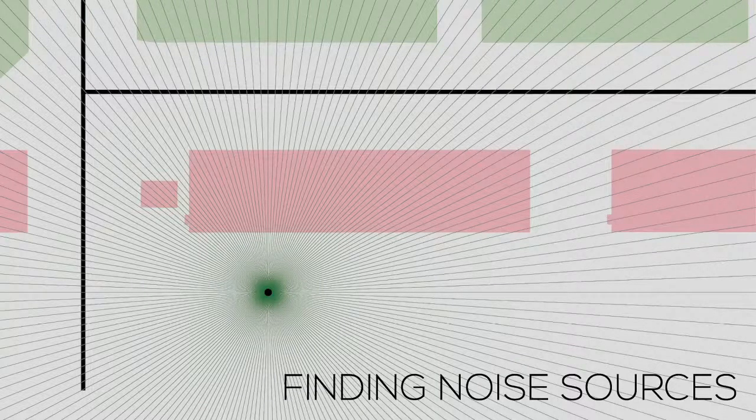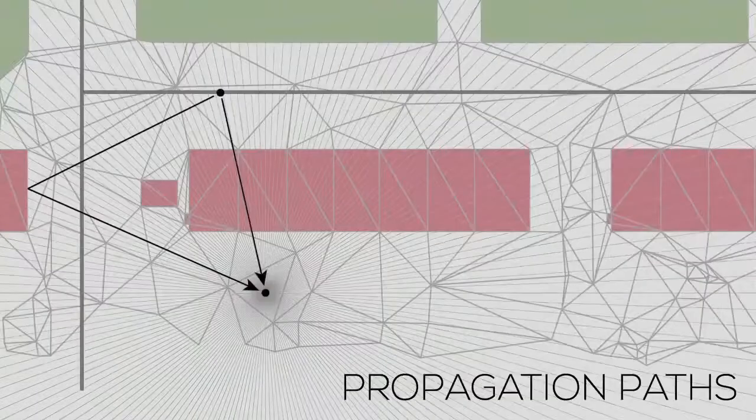Our client requested us to use a method where we search for the intersection point between 2 km long rays coming from the receiver with a 2-degree interval and the road elements, as can be seen in the slide. The length of the rays is specified in the European Standard for Noise Modeling. Using these source-receiver pairs, we can find the different propagation paths, either direct or reflecting.